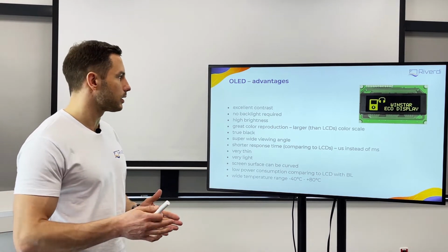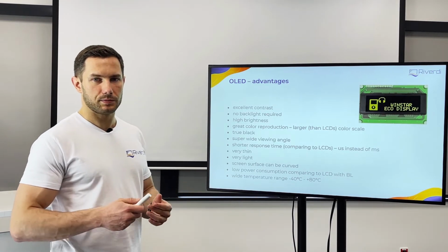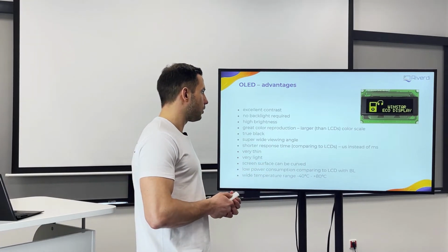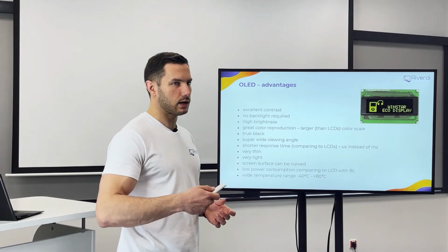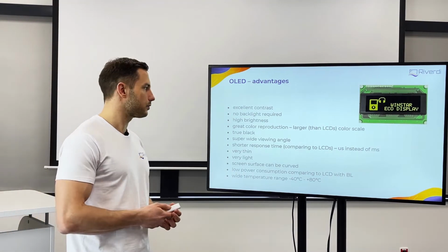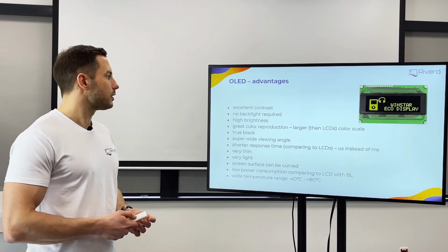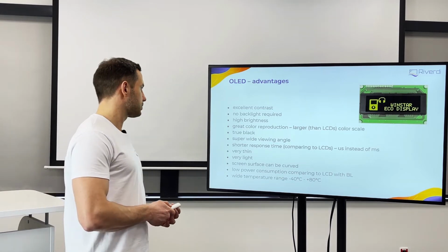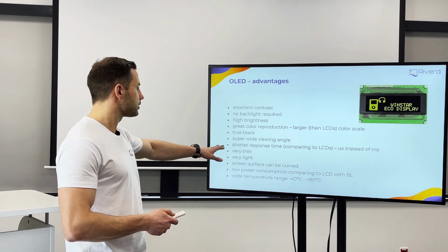We are able to generate very saturated colors in a wide gamut. Typically, OLEDs have the widest color gamut on the market, and it's really superior to a typical TFT. Of course, we can achieve this with a TFT, with special color filters or quantum dot filters, these kinds of enhancements of the TFT, but in general, OLED will be superior here without any special layers, anything like that. So it's true black, it's related to the contrast.